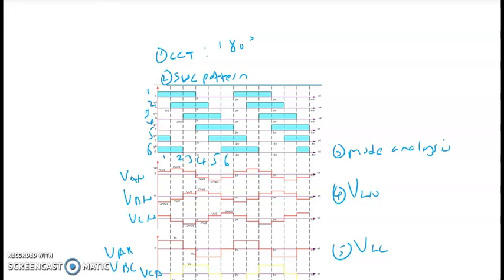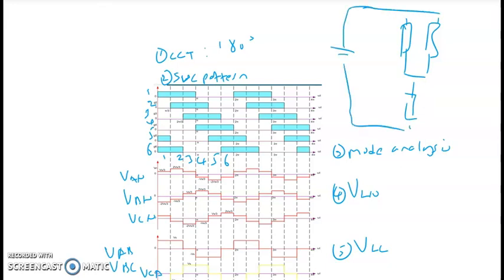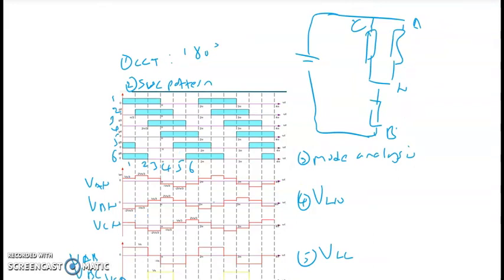Like just now, when on mode 1, from the circuit we have the pairing of A and C. The current comes into A and C, goes up to N, and returns through B to the source.